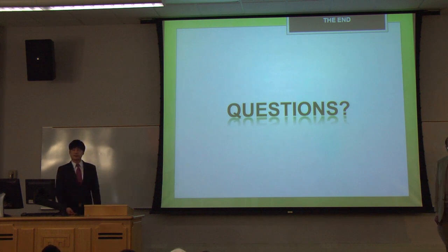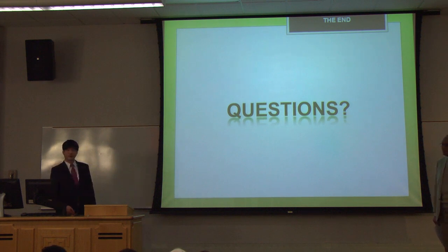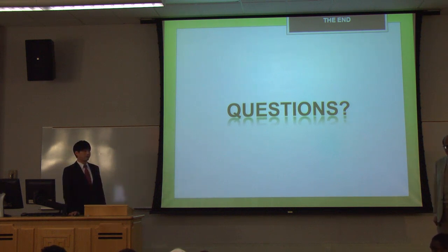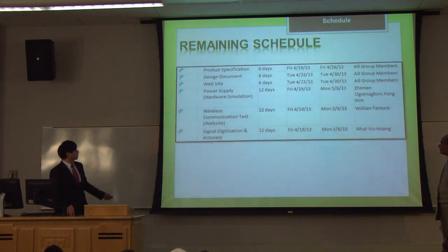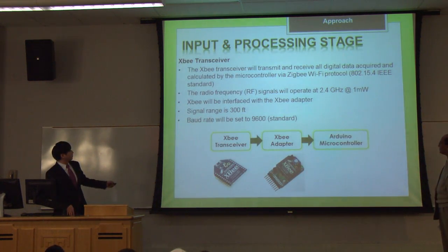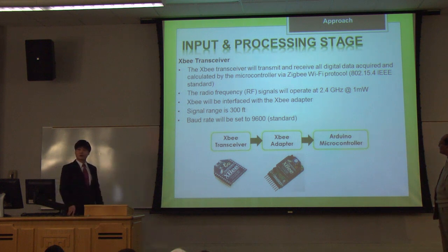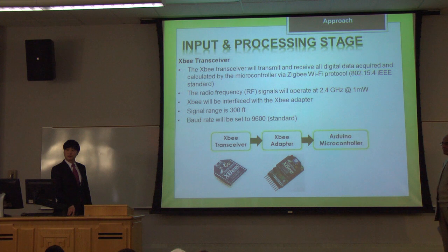Do you know the XP transmission rate? The bit stream rate? Yeah, the transmission rate. We're set at 9,600. That's the standard value. Baud rate, which is bits per second, yes. Did you calculate for 300 feet? Probably even less than that, right? Because of signal degradation.